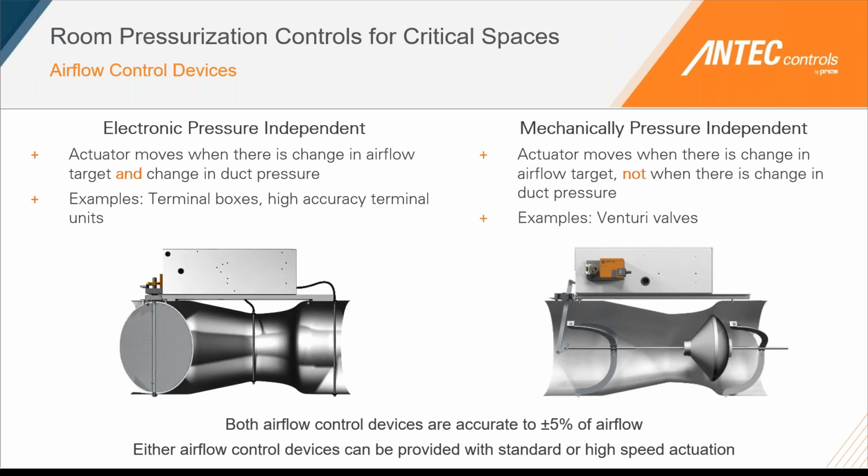But the newer style venturi valves, especially the ones that we provide Antec controls for, are designed to take that out. So you're not going to see the same issue of the valve losing accuracy at 10, 15, 20 years due to linkage slop. It's a really great question. Potentially we'll follow up with you and provide some additional resources that you can find on our Antec Controls website.